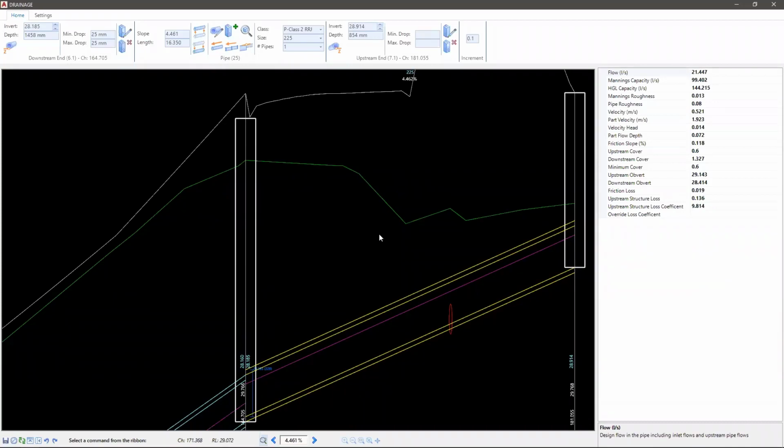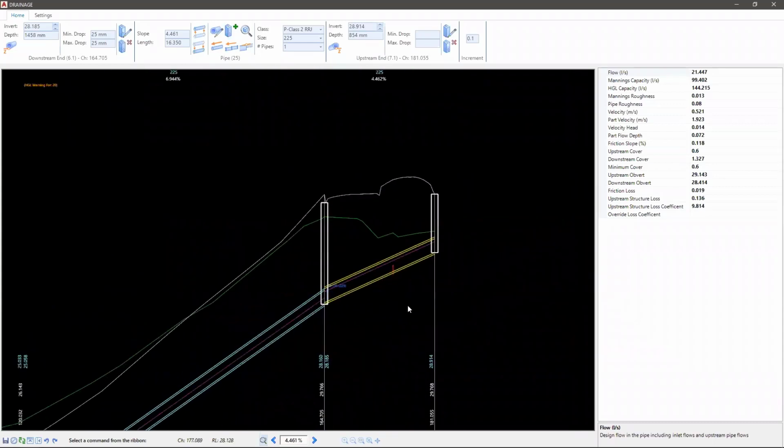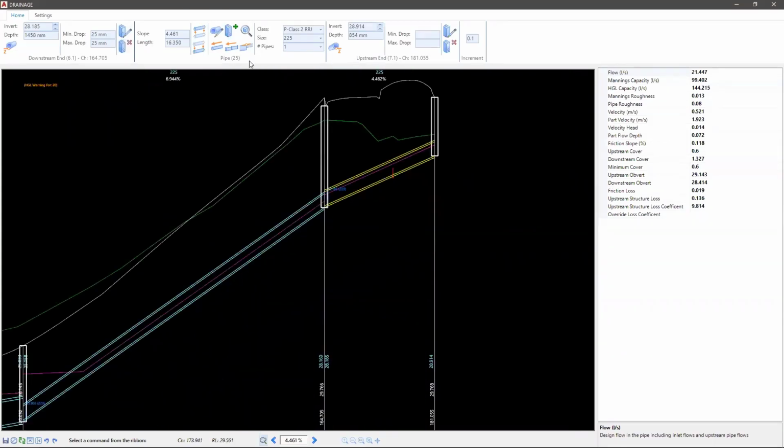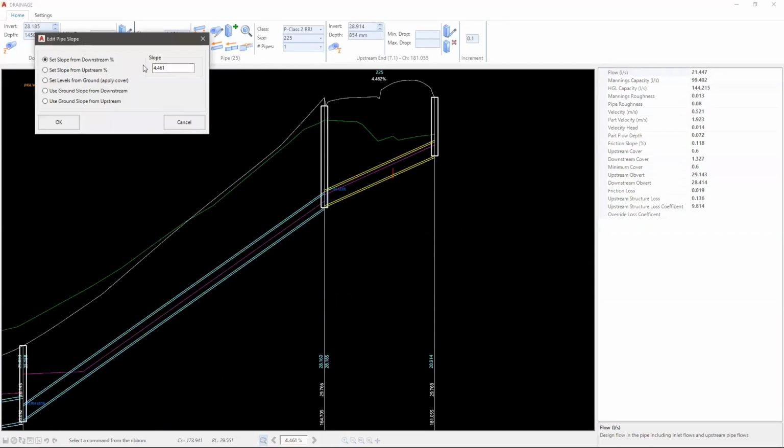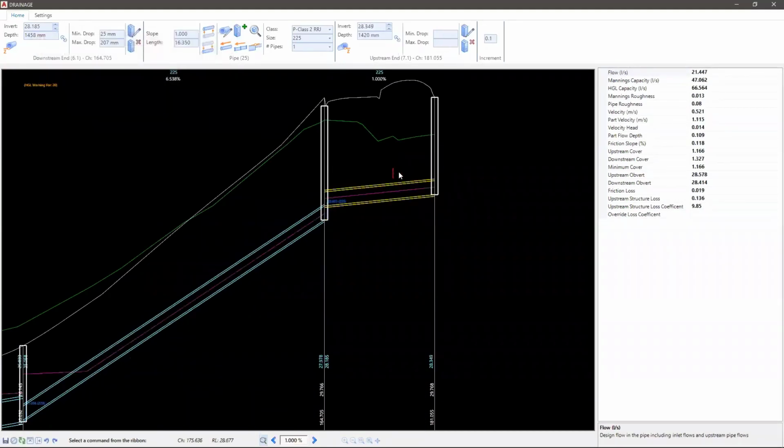So not only are you going to be able to see your pipes in 3D, but then obviously able to analyze them in respect of clashes and distances. So not something that we're looking to develop within the VGE. The only thing you get in terms of clash detection, depending on the cover controls set on the pipe and the crossing object, is that it will change color up here to indicate you're outside your zone, but it won't give you the distance.